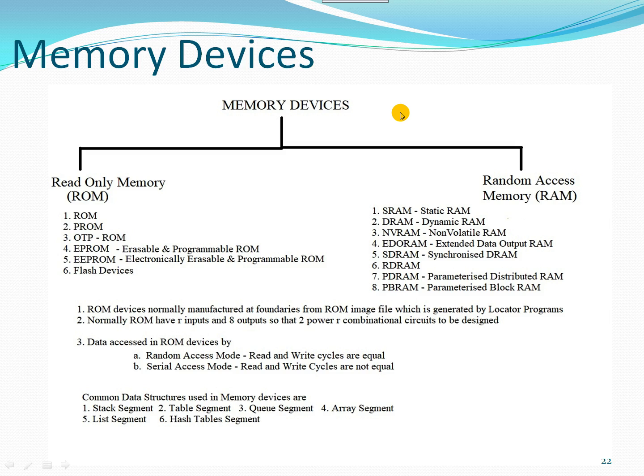The heap segment is required in an embedded system where we have some mathematical calculations or some programmable calculations, so that the variables, the static or the dynamic variables, are going to be stored inside a heap during the execution of the program. So for that we need to have some heap segment also.